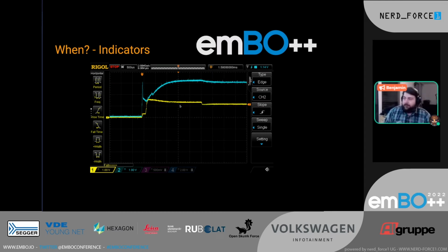And now we continue on, and suddenly there is another drop. And this is a really sharp drop. Let's just say we can interpret this as a memory controller for the flash memory coming online. Because up until the configuration region is being read, everything is executing from the internal bootstrap ROM. But now we need access to configuration memory, which is likely implemented as flash memory. And reading flash memory, you need to power up its memory controller, and reading flash memory also costs additional energy. So let's just say this is the voltage drop we are looking for, because now reading configuration starts.